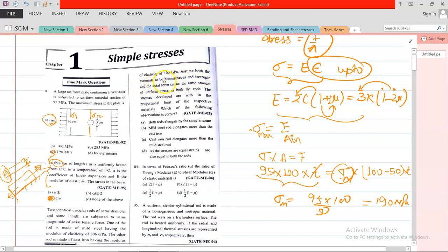What do homogeneous and isotropic mean? The Young modulus at any place is the same, equal to E. That is called a homogeneous material. Now isotropic means that in any direction your E doesn't change. Suppose this is your material, at one point this is point 1, this is point 2. At these 2 points your E will be the same, then it is called homogeneous. Now in this direction it is also E and in this direction it is also E, so it is called isotropic.